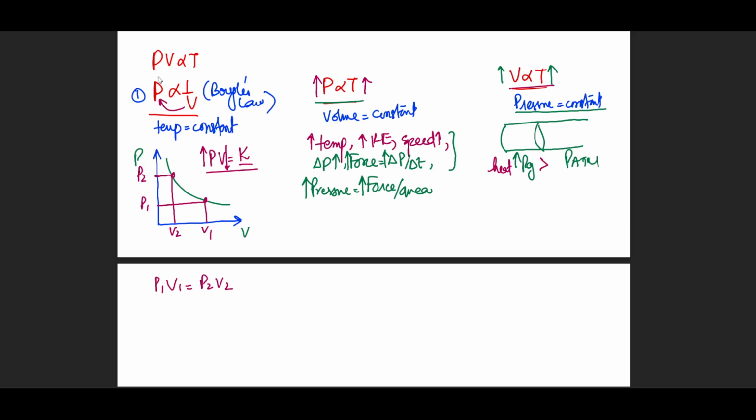And as it increases, because of the temperature, as we've already explored, the gas molecules apply a force from the inside, which is a bit greater than the external force due to the atmosphere. So the piston of the syringe moves slightly forward. Now, when it moves to the new position, since volume has increased, the pressure drops due to Boyle's law. When the pressure drops, they become equal again. Now, when they become equal, the syringe is seen to be holding this position.